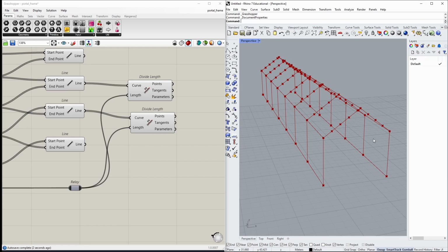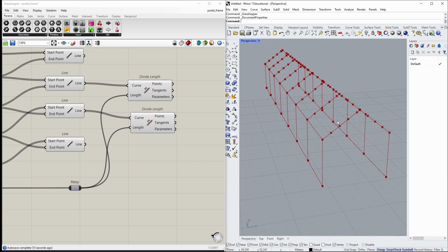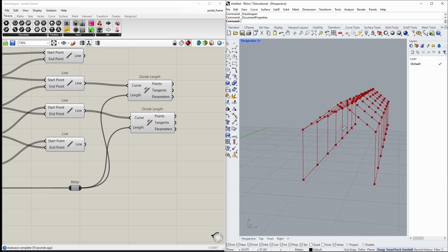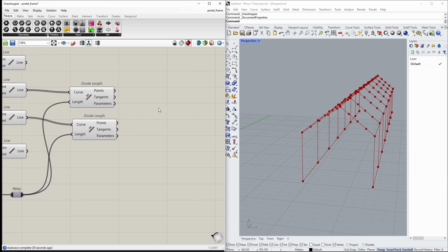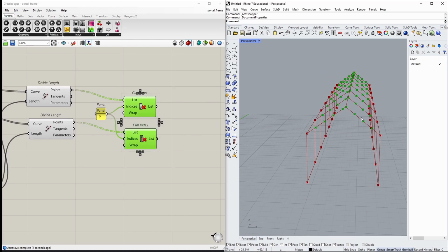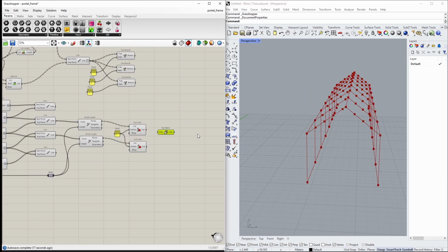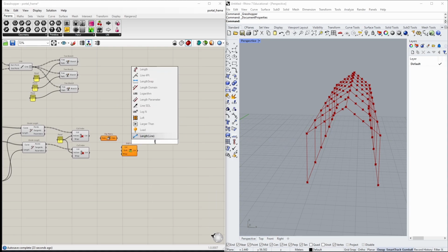Because this component starts at the start point of a line, meaning here and here, where there is already a line, and we don't want a redundant line, remove those points with List Item. Provide the 0 for both, take the points into these components, and we got what we wanted. Then it's flip matrix time, and we do that whole shenanigans once again.